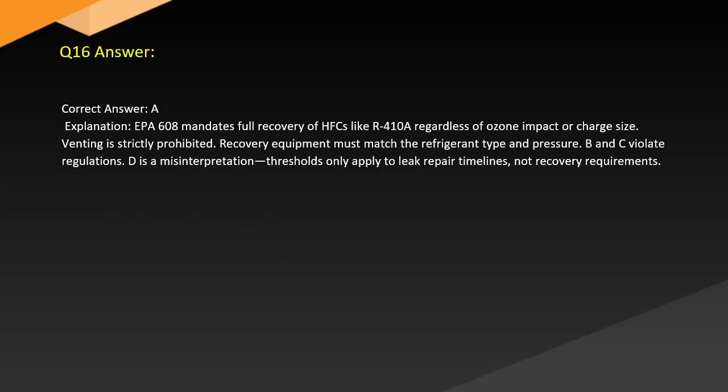Answer. Correct answer: A. Explanation. EPA 608 mandates full recovery of HFCs like R-410A regardless of ozone impact or charge size. Venting is strictly prohibited. Recovery equipment must match the refrigerant type and pressure. B and C violate regulations. D is a misinterpretation. Thresholds only apply to leak repair timelines, not recovery requirements.